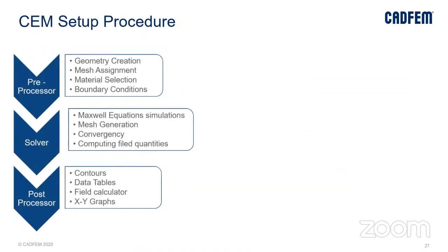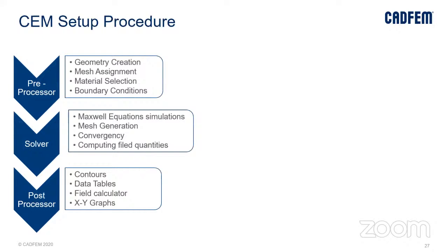And for the CEM procedure, if you want to follow this, generally we need a CAD geometry for the computational electromagnetic model setup part. Either you can create from templates, because a couple of applications already have templates, like motors and transformers, the electronic transformers or toroidal structures. Such things have pre-existing templates which automatically help you create the geometry. Or otherwise, you can directly integrate your own CAD formats.